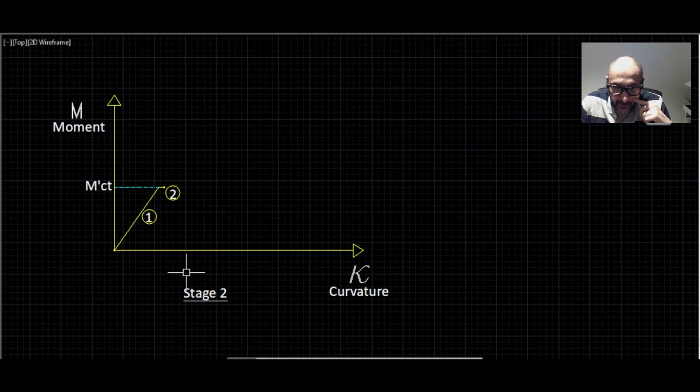Now, I have a question. Do you think that this external load P star was the only force, or the only two forces, which would cause that first crack? And the answer to that is no, because generally when we pour concrete, we have early shrinkage drying cracks, okay? And these cracks are formed initially before any loads. They create these tensile stresses at the bottom, and you get microscopic cracks within the tensile region of the beam. Okay, so we do have very minor cracks that happen due to the early shrinkage drying cracks.